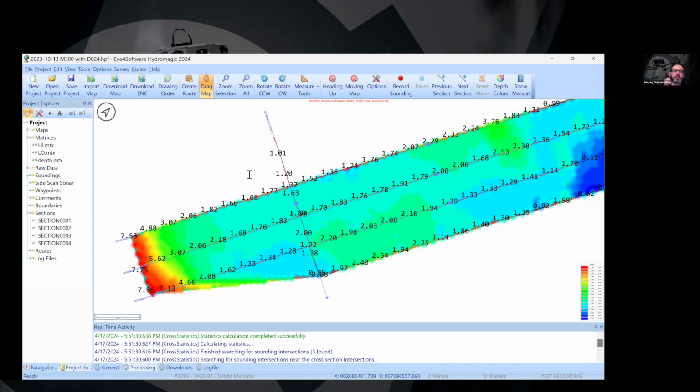Actually, it is absolutely the same with a manned or unmanned boat, because they will go with the waves up and down. And if you fly in RTK mode or with a PPK receiver, you don't need to do any additional steps to account for waves. Everything will be done automatically.